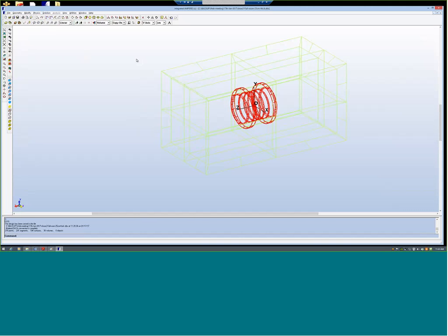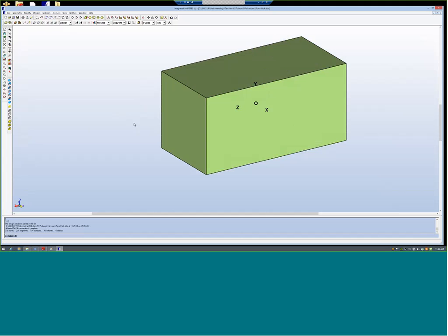So when you are using the boundary element method, for the source coil part only you have to use 3D mesh, as we already saw. On the steel part, you need to assign 2 kinds of mesh, because the material we have taken is nonlinear. Because it is a nonlinear material, in those volumes you have to use 3D mesh.